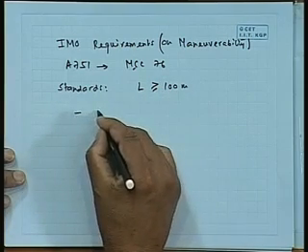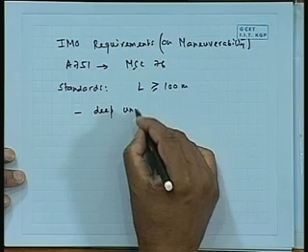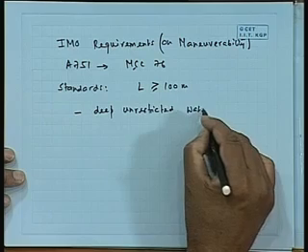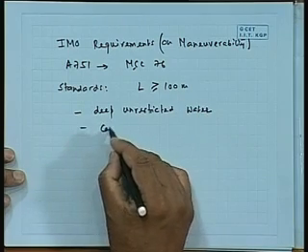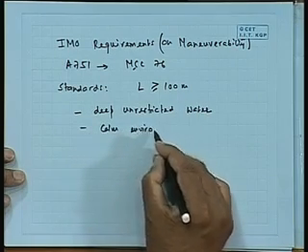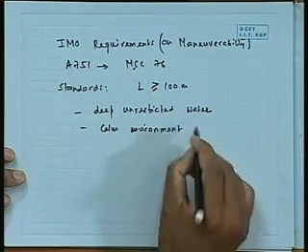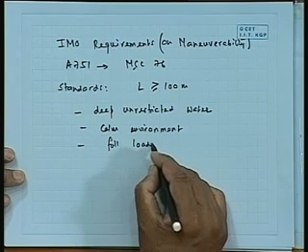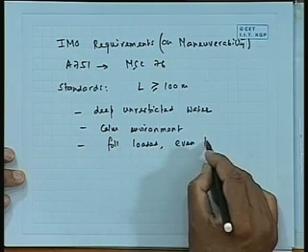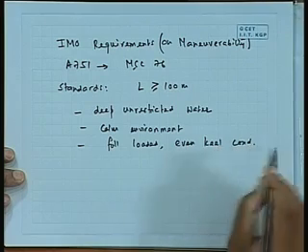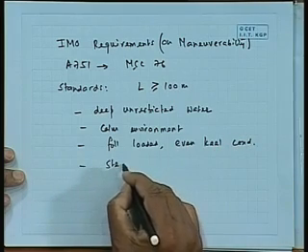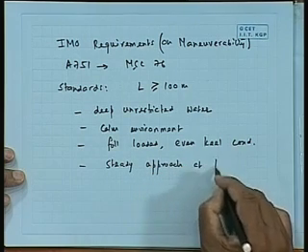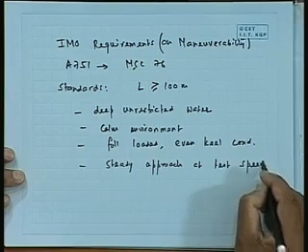And they should be done in what is called deep, unrestricted water and in a calm environment, for only the fully loaded condition, and steady approach at test speed.